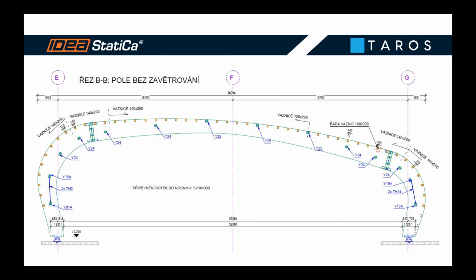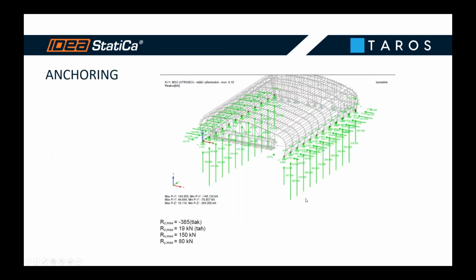This is the part without bracing, and we will focus on the anchoring here. You can also see the assembly joint here. It was due to the transportation limits. It consists of 3 parts: this column, the short column here, and the main beam in the middle. There are also steel parts to fix the struts, timber purlins. It has a quite lightweight build-up of the roof. Okay.